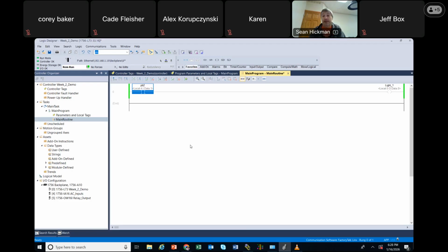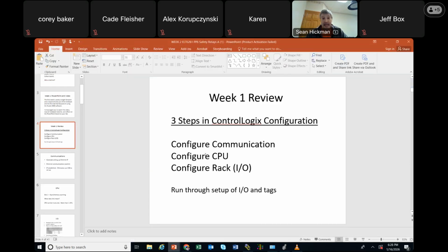Now the problem is you can't be a PLC hog. You can't hog the PLC the whole time generating your program online because your partner wants to download it as well. But a lot of times when I'm programming and building something up, I do a lot of it while I'm online. Now, you wouldn't really do that out in the field because everything that you're doing online is going to affect the machine, and you don't really need to blow that work cell up by making all these online edits. But if you do need to make something small, double click, boom, change it, and click the green arrow. So you're going to become overly reliant on this, unfortunately, but hey, it works good. All right. So I did that.